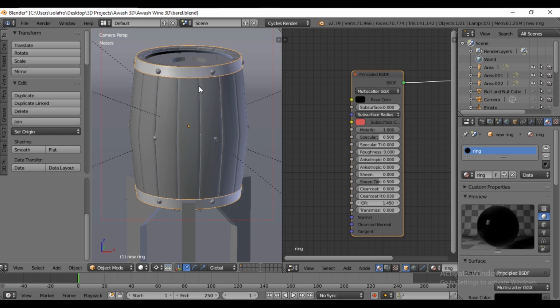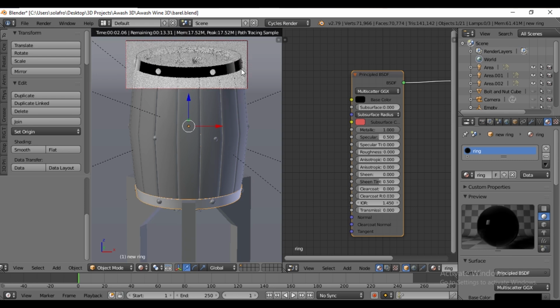To view the material specularity without roughness, press Ctrl B to select the render boundary and switch to render view. The material appears shiny, which is undesirable as it compromises the metallic properties. Adjust the roughness value to 0.2 or lower.